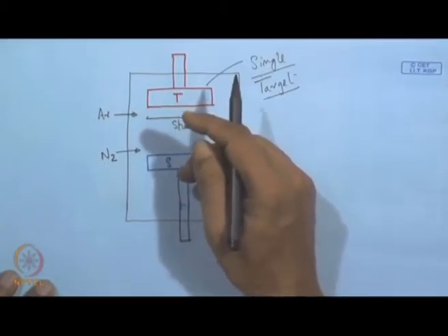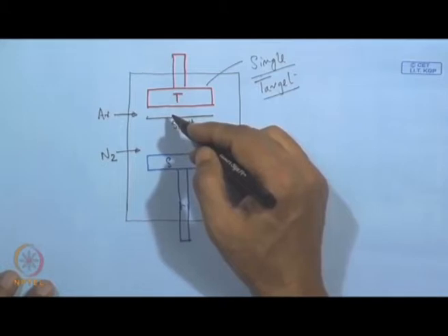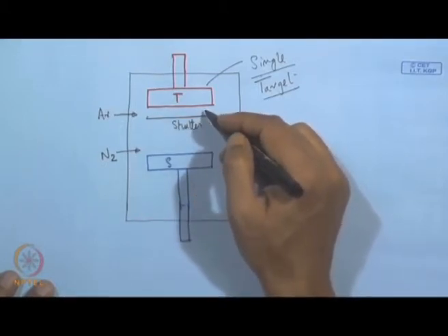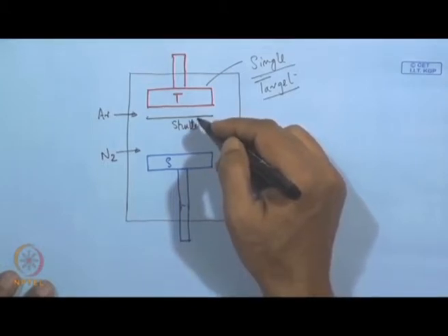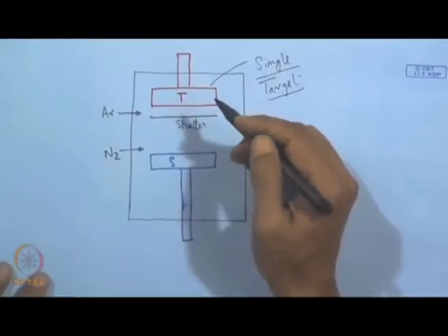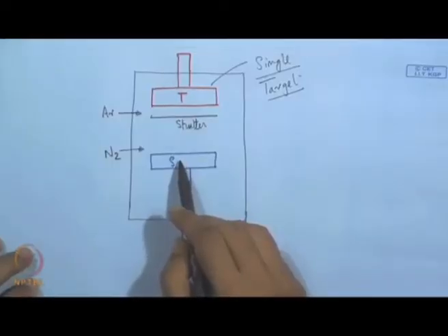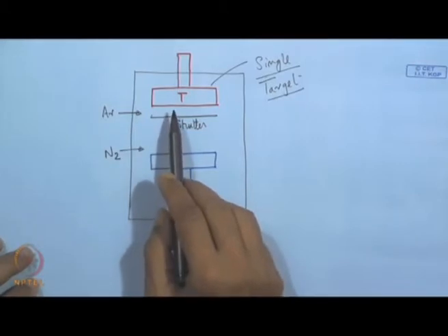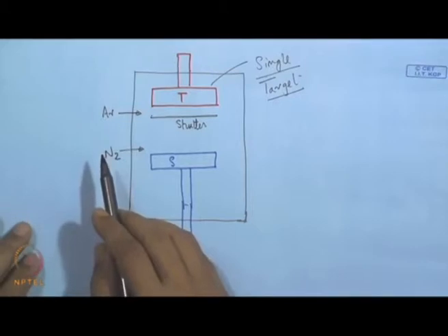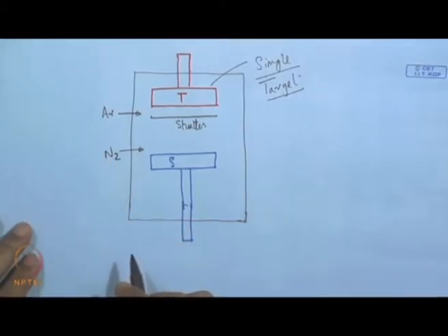the surface of the target, because it is not necessary, and at the same time it is also not desirable. The reason is as follows: if we have nitrogen on this side, we can have target poisoning, and we immediately have nitride formation on the target, and then the sputtering rate and the energy requirement, everything will keep on changing, and the whole principle or idea behind reactive sputtering will be totally defeated. So, clearly the idea is that nitrogen should be available close to the surface of the substrate, while argon should be very close to the target. With this arrangement one can start the sputtering process.